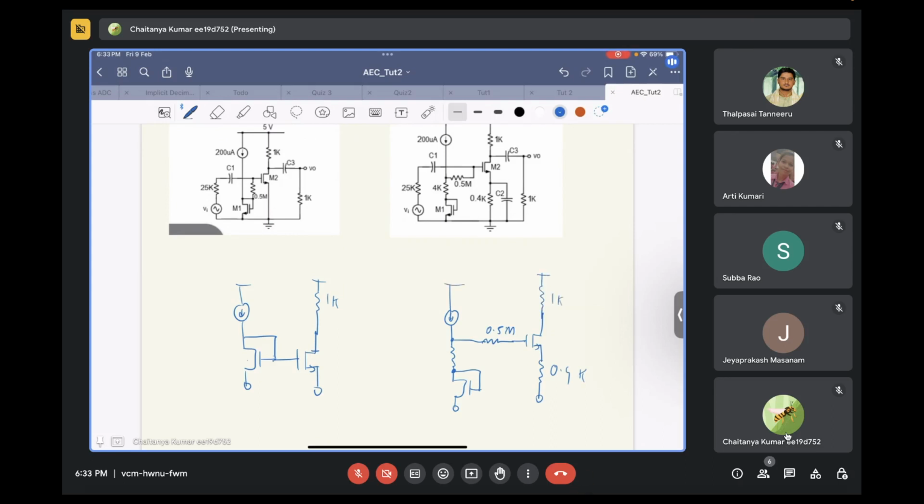So we have these two circuits, correct? Can you see how I drew both the circuits? Okay. Now, we said that in this circuit, if there is a VT variation, as long as that VT variation is the same in both the transistors, your circuit will remain immune to VT variation. Do you understand this?